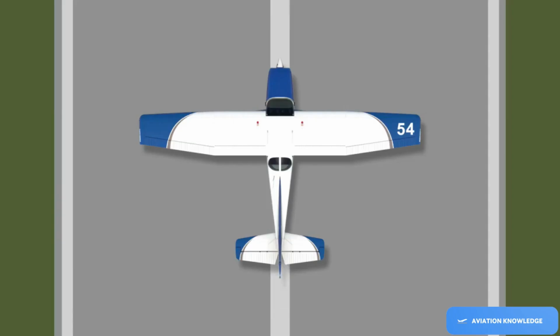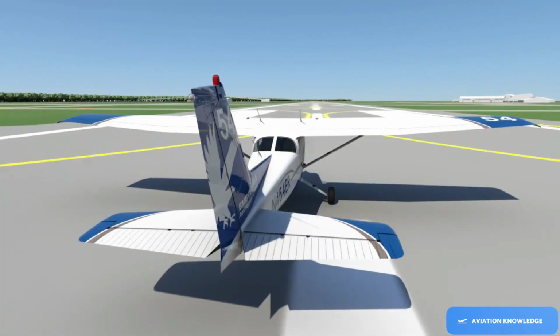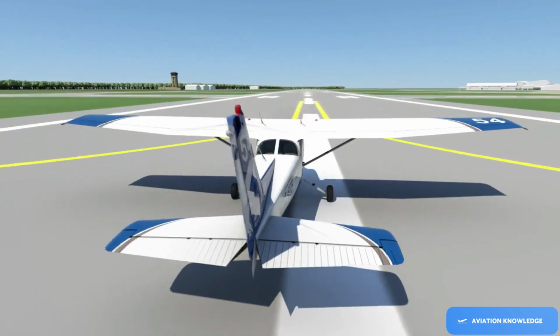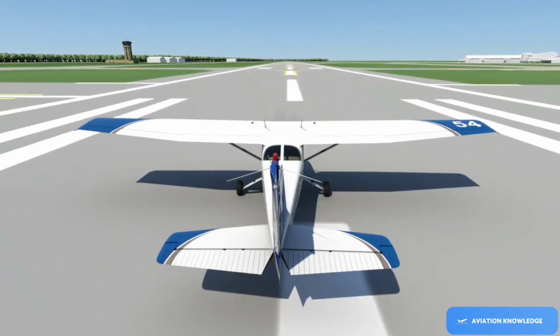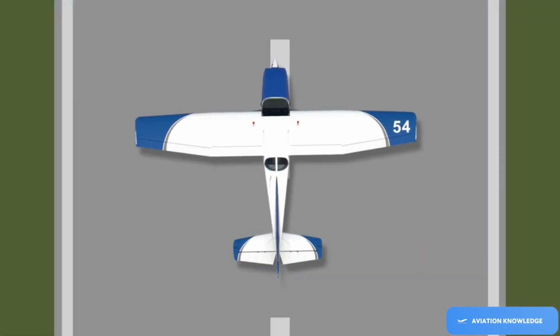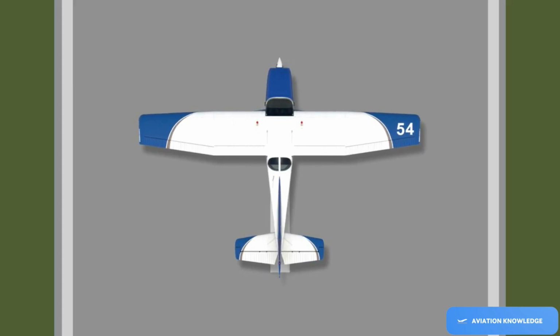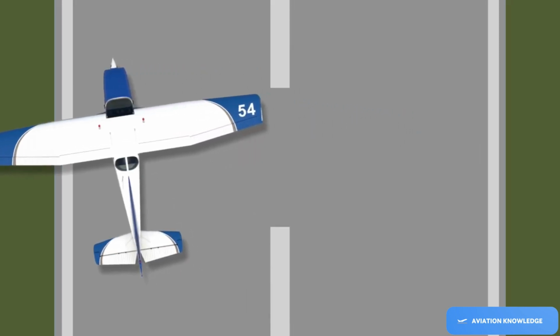As the Cessna starts to accelerate down the runway, you may notice a tendency for the plane to turn to the left. You will need to add a slight amount of rudder to counteract this and keep the airplane on the center line. Continue to make small rudder pedal inputs to maintain the aircraft on center line. Make the inputs as soon as you start seeing the airplane drift from the runway center line. Waiting too long to correct could result in a runway excursion.